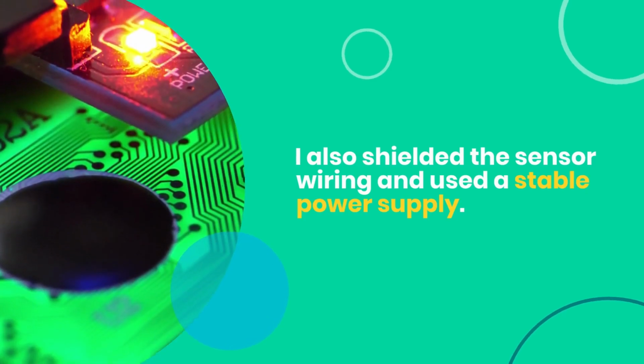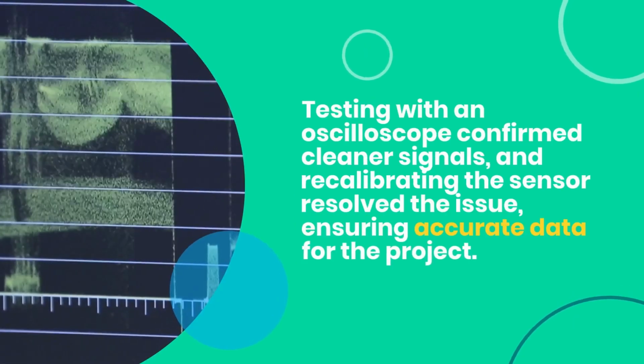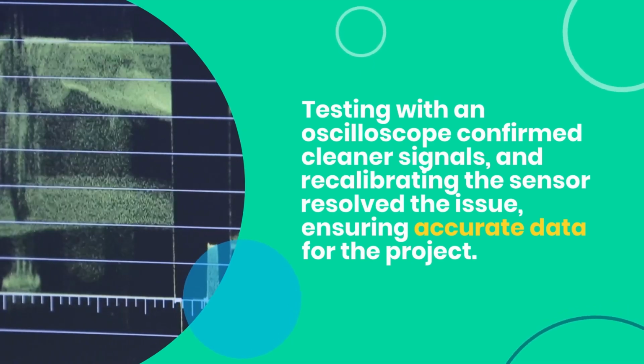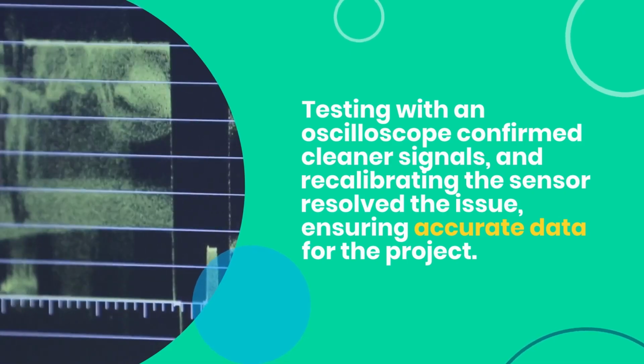I also shielded the sensor wiring and used a stable power supply. Testing with an oscilloscope confirmed cleaner signals, and recalibrating the sensor resolved the issue, ensuring accurate data for the project.